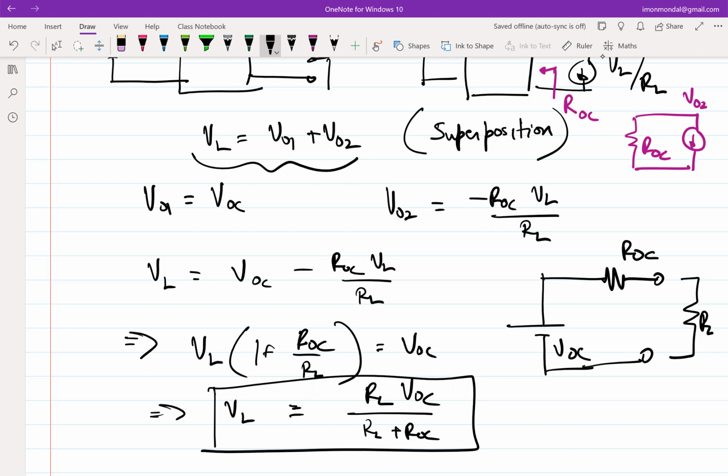Okay. And from the perspective of a designer, it also makes life simpler for you. Let's say you want to sell a product, you want to attach whatever you have designed to any particular load. You don't have to go and tell the seller or your friend who is using your circuit how the circuit is made. That information is unnecessary. All you need is the open circuit voltage and the output impedance, right? These two pieces of information make life easy. Again, a layer of abstraction, right? Layers of abstraction are used to make life simple, and this is one example of that.